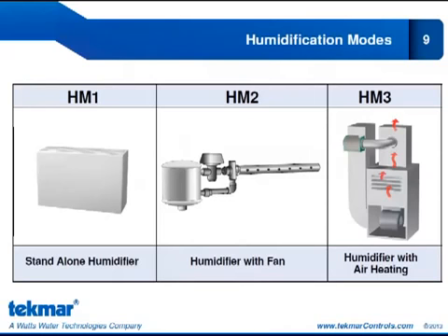And an example of this, as shown on the slide, is a steam injection humidifier, where water is boiled and steam is injected into the duct. Now, we do need that fan to carry the moisture in the air to the space.